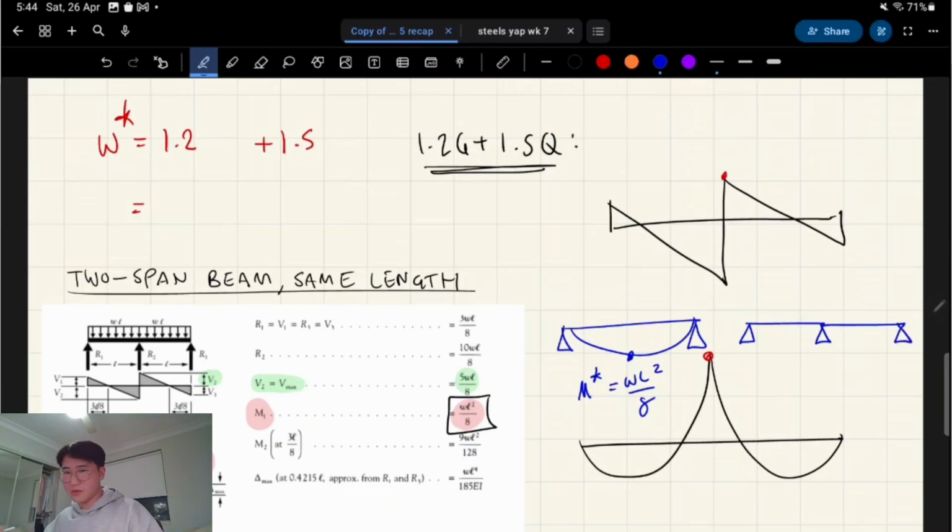If you had a continuous beam with 2 spans, what you'd expect to see for the bending moment is this. But do you reckon that the maximum bending moments in those spans are less? If you think yes, you're correct. There's less of a positive moment, but the maximum moment will be over the middle support now. And the magnitude of that just happens to be the same as the middle for a simply supported beam.